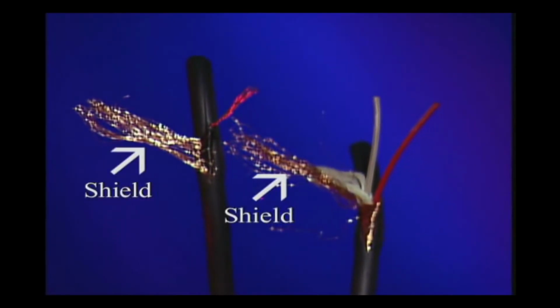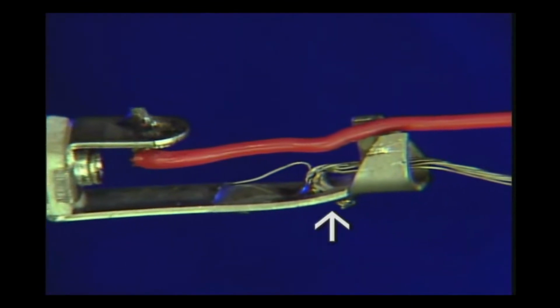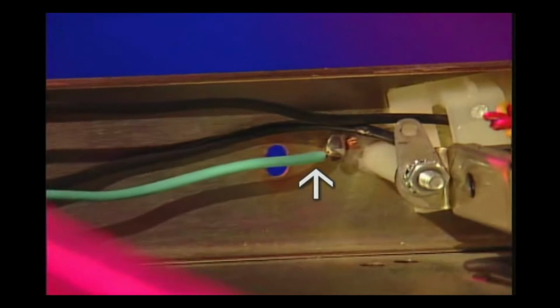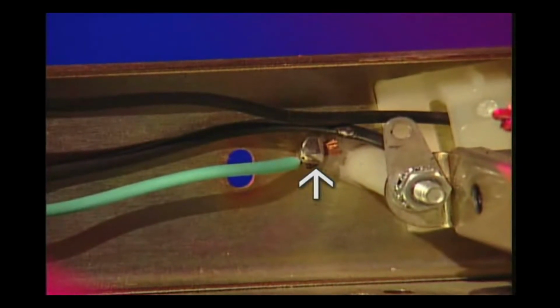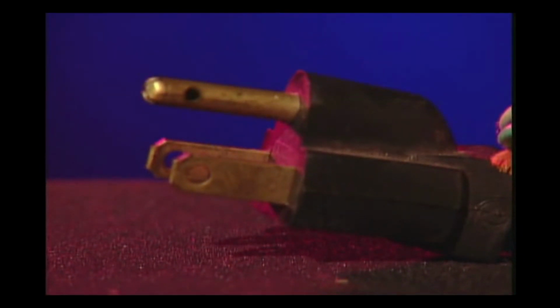In every cable, connector, and electrical device used in an audio system, there's a grounding capability. In a cable, it's the shield. In a connector, it's the sleeve or a pin. In a device, it's the chassis ground. The purpose here is to maintain the flow of ground throughout the system until it can safely be carried, ultimately, to earth through the 3rd prong of a 3-prong AC plug.